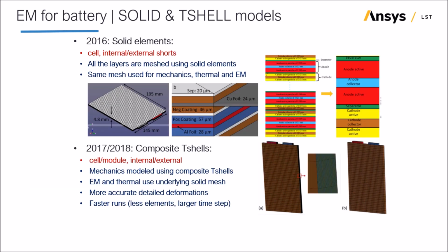For instance, the detailed layers in the cells are important electrically and thermally, but less so structurally. So the model can use a layered thick shell for the mechanical analysis, while automatically creating multiple layers of solid elements for use in the electrical and thermal calculation.